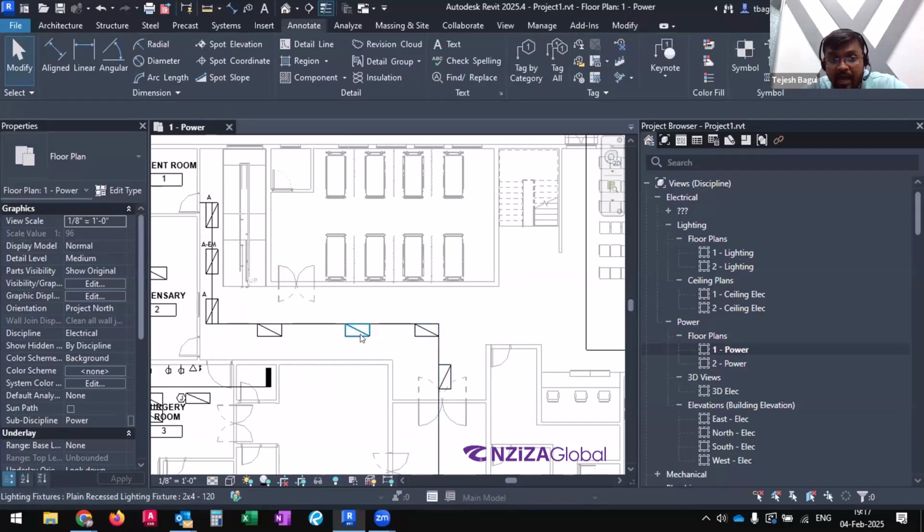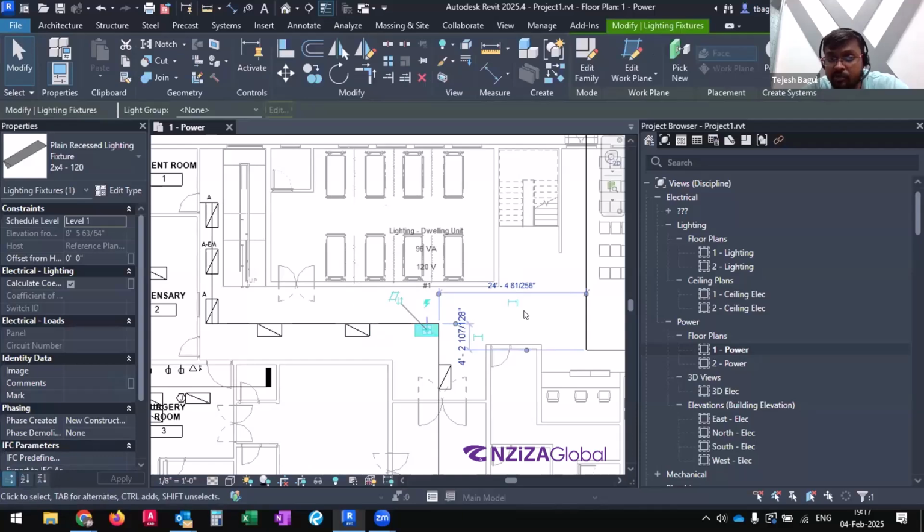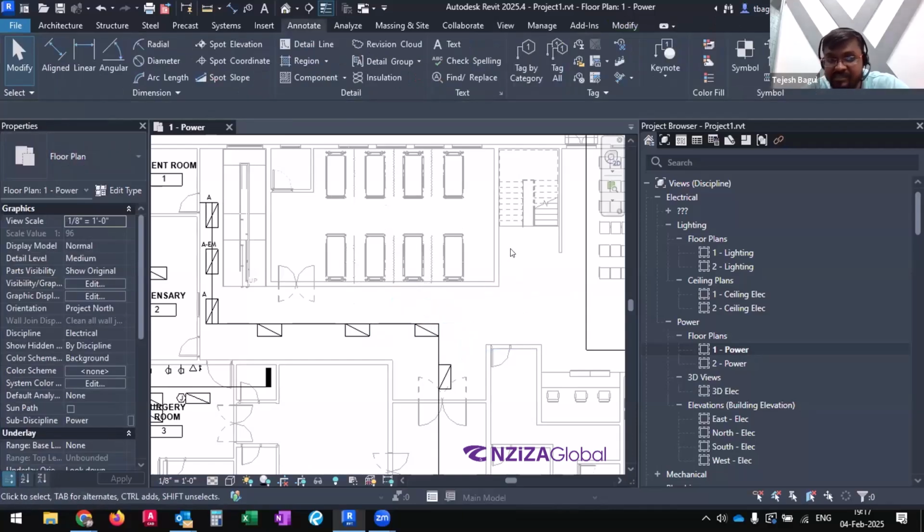So it would be better to have maybe this or this particular light fixture on emergency, so that if a person is trying to exit from here, they will have this light fixture providing adequate foot-candle levels in this part, and then when they come to this side, maybe this or this light fixture will illuminate this path accordingly. So make sure you make a good judgment call so that there is no dark spot or blind spot for the path of egress.